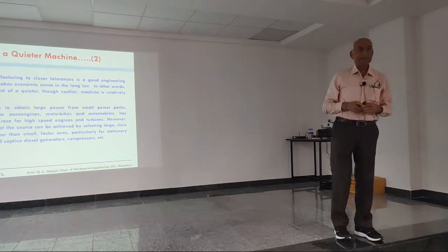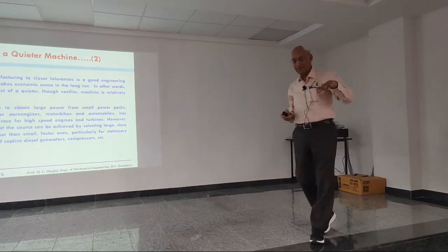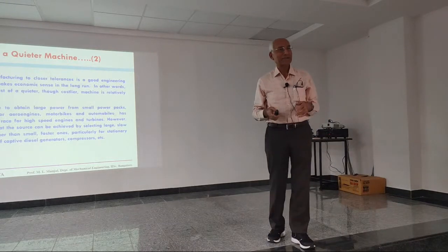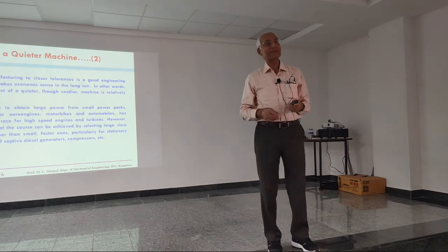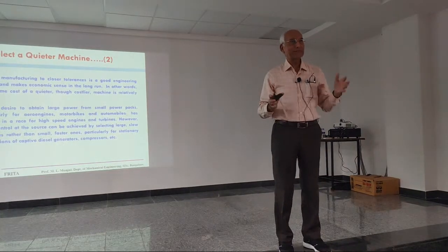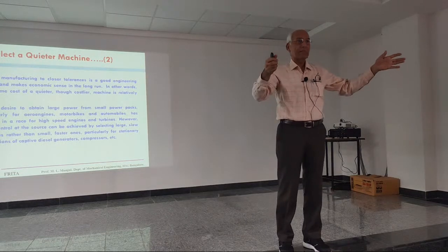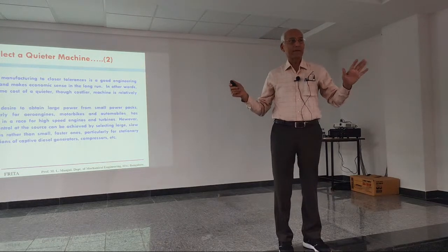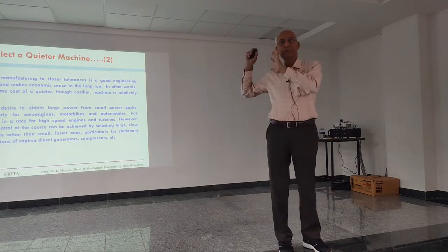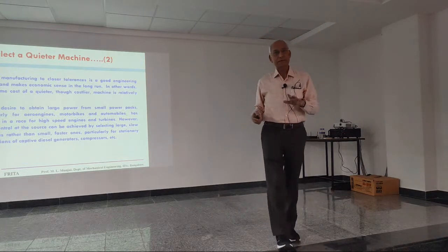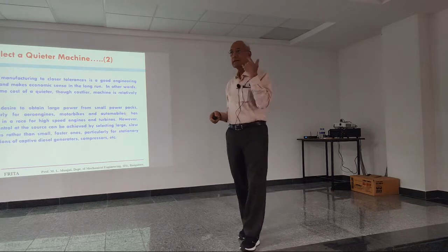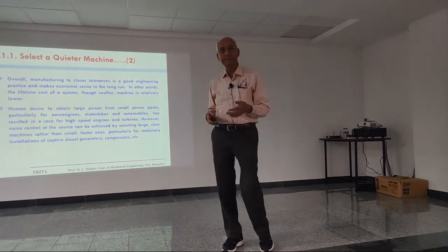In fact, now let me just tell you, I have been selling this idea to defense. In our ships, etc., I've been telling them that please slow down. Let it be a large engine running at smaller speed, and you will find that most of the problems that you're facing are not there. Not just from a noise point of view, but from wear and tear, the endurance life, and everything.